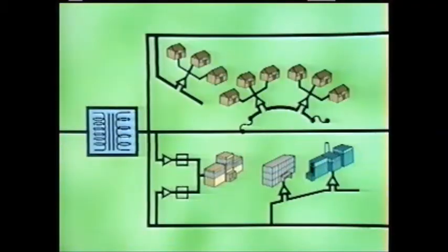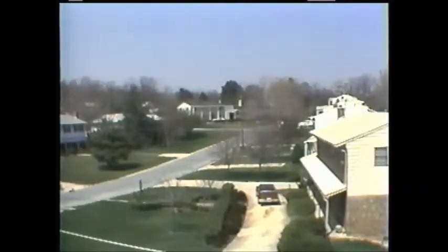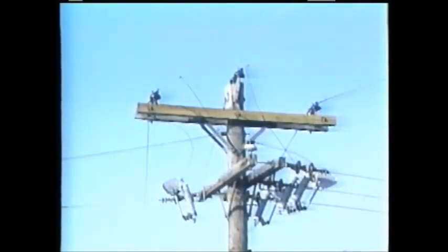In this part of the program, we've identified three types of distribution lines: the feeder, the lateral, and the service drop. We've explained the type of voltage each line carries, and we've shown you three types of distribution layouts. Regardless of how a distribution system is designed, the lines and components must be protected from damage due to faults and voltage surges. The customer must also be protected from outages. We'll take a closer look at protection and protective devices when this program continues.